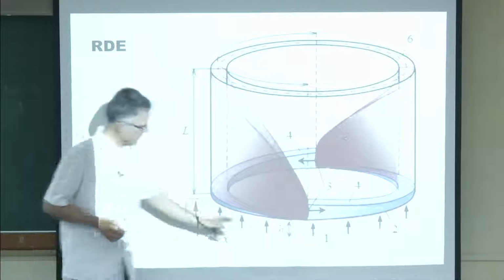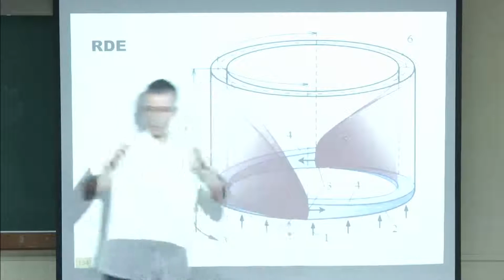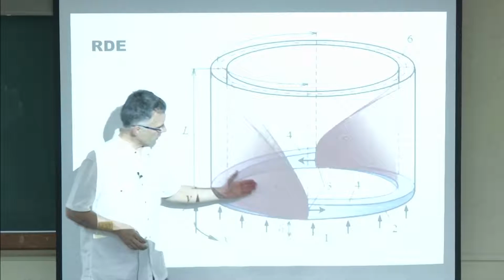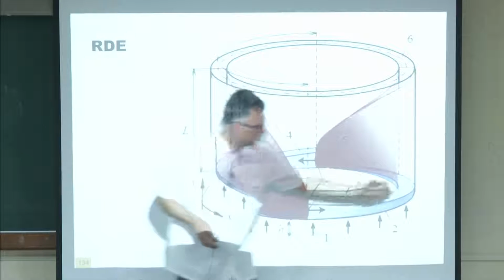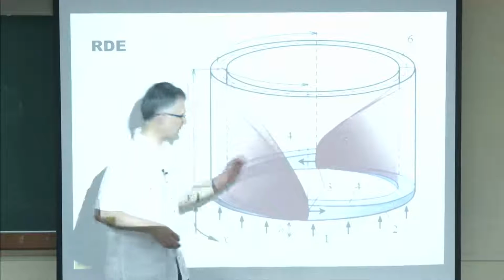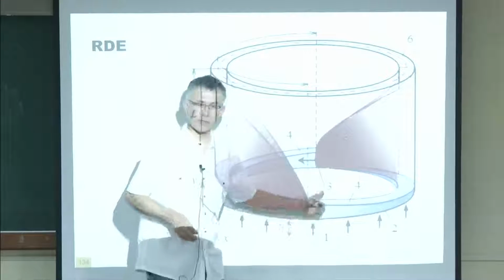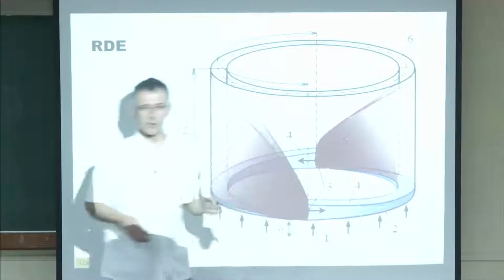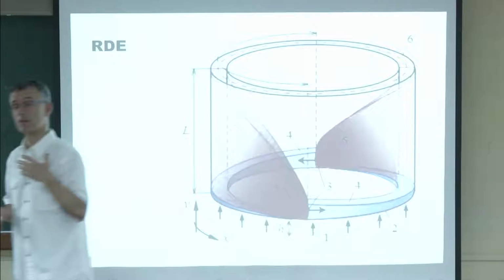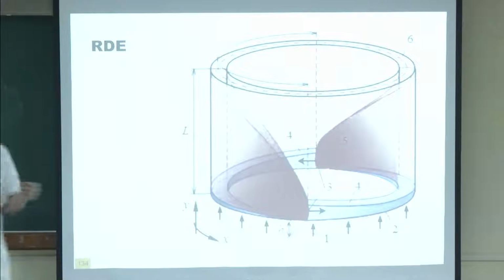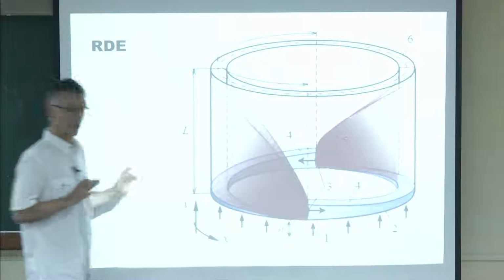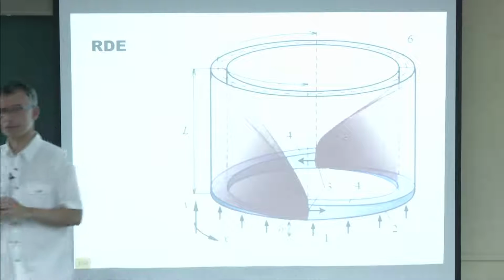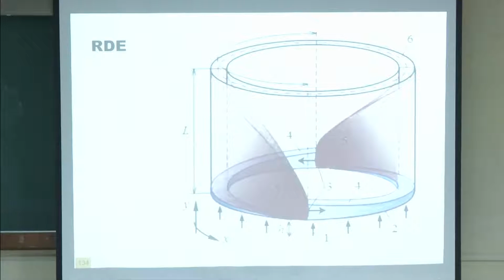You would inject premixed gases, well, almost premixed gases at the bottom of the chamber, and then the detonation wave will turn like this, go into the other side, come back, and by the time it comes back, you will be able to inject more premixed gases, and this thing would keep turning. But the efficiency of a system like this would be very large on paper, if you can make it work, because it's complicated, because the detonation goes so fast. Okay? So if you do the computation, you see on paper it's efficient.